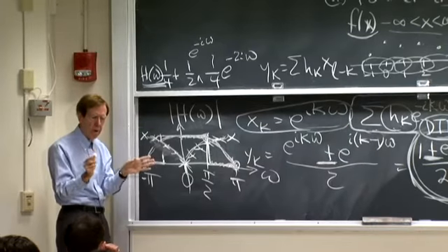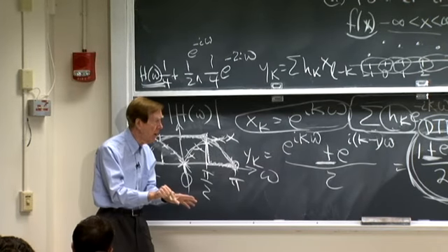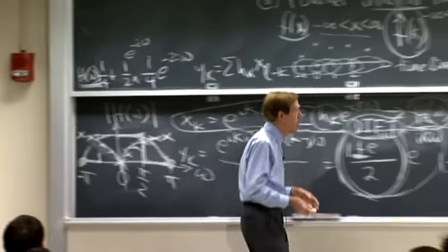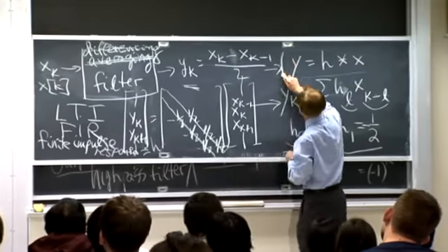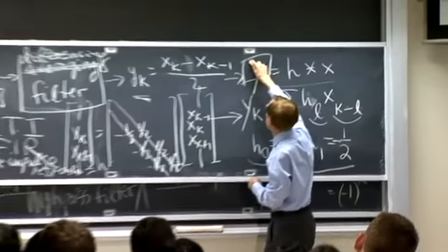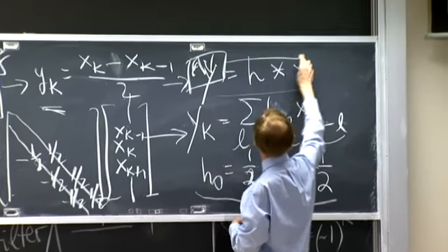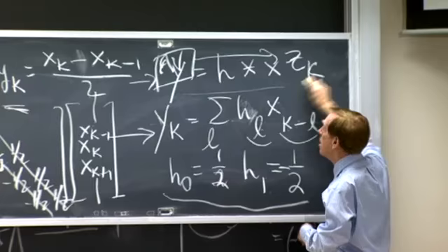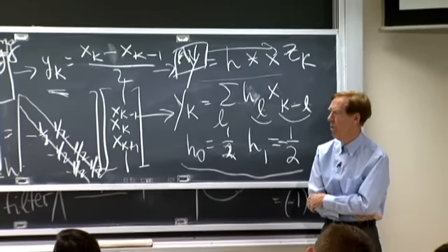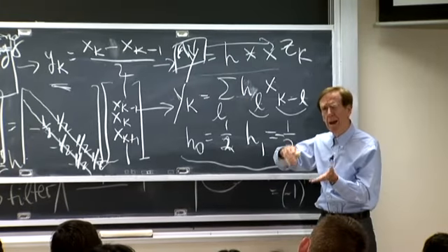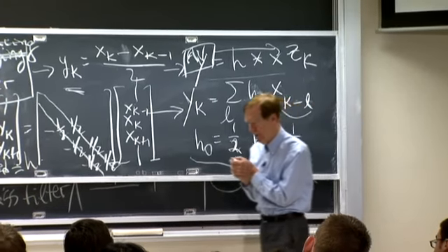If I do an average and then I do the average again, in other words, if I just send these signals y_k through that same averaging filter, so average again, to get a z_k, I think probably the coefficients would be 1/4, 1/2, 1/4, and I've taken out more noise, right?